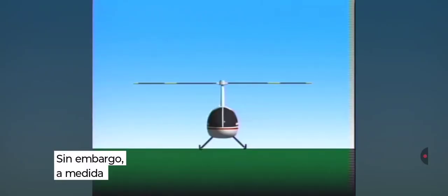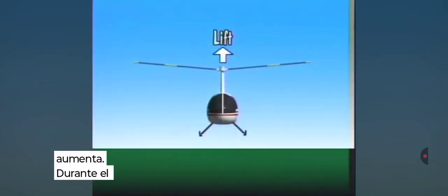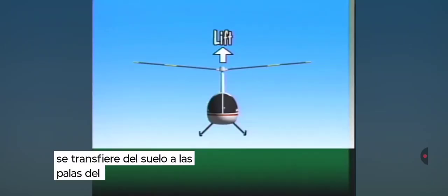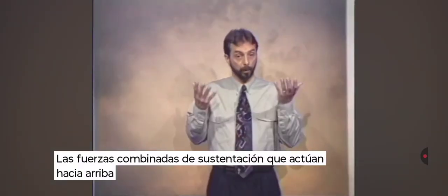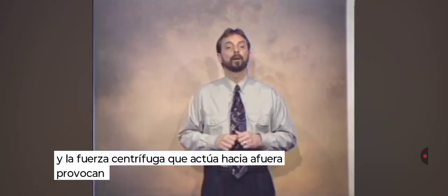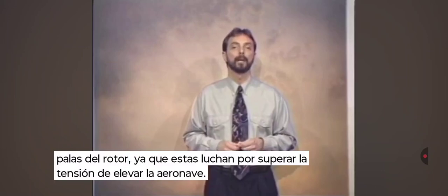But as the collective pitch is raised, increasing the angle of attack, lift is increased. On takeoff, the weight of the helicopter is transferred from the ground to the rotor blades, and the aircraft is literally hanging from the blades. The combined forces of lift acting upwards and centrifugal force acting outwards cause an upward flexing of the rotor blades as they struggle to overcome the stress of lifting the aircraft higher.